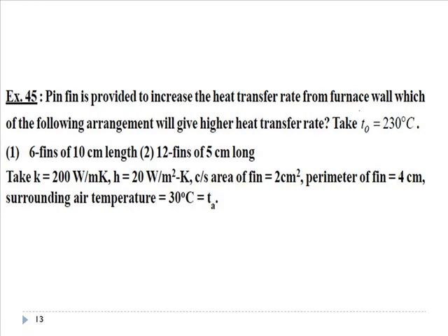Take thermal conductivity equal to 200 watt per meter Kelvin, convection heat transfer coefficient equal to 20 watt per meter square Kelvin, cross section area of the fin is 2 centimeter square, perimeter of the fin is 4 centimeter, surrounding air temperature TA is equal to 30 degrees Celsius.